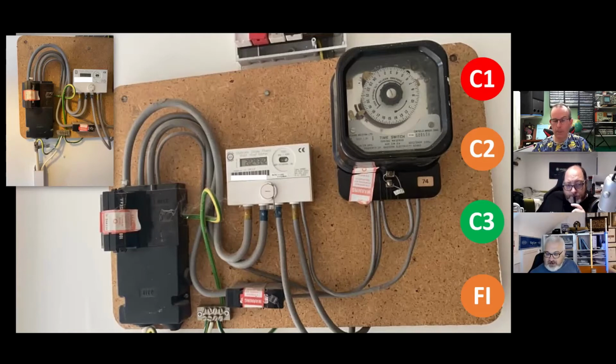Yeah, because the PME labeling is really weird. They've only just revised their standard to mandate PME labeling now, which is bad, because they were able to get away with not PME labeling it before. I would suggest that there was a TN-S there at some point. Somebody has probably made some form of effort to put a bigger, thicker conductor on. And then eventually the DNO have come out, and they have also PME'd it.